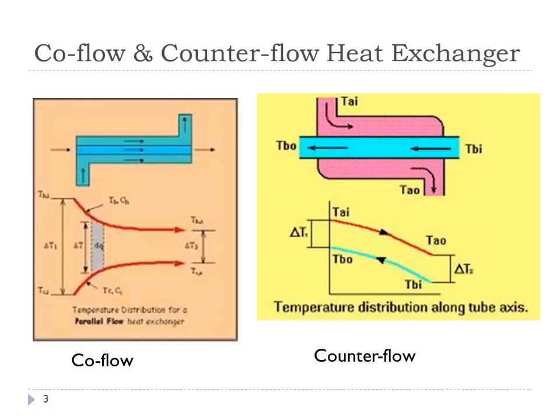Whereas in the counterflow case, you can get your temperature on the outlet of the cold side to be above the temperature of the outlet on the hot side. You're only constrained in that case by the actual temperature on the inlet of the hot side. And that's going to be key.